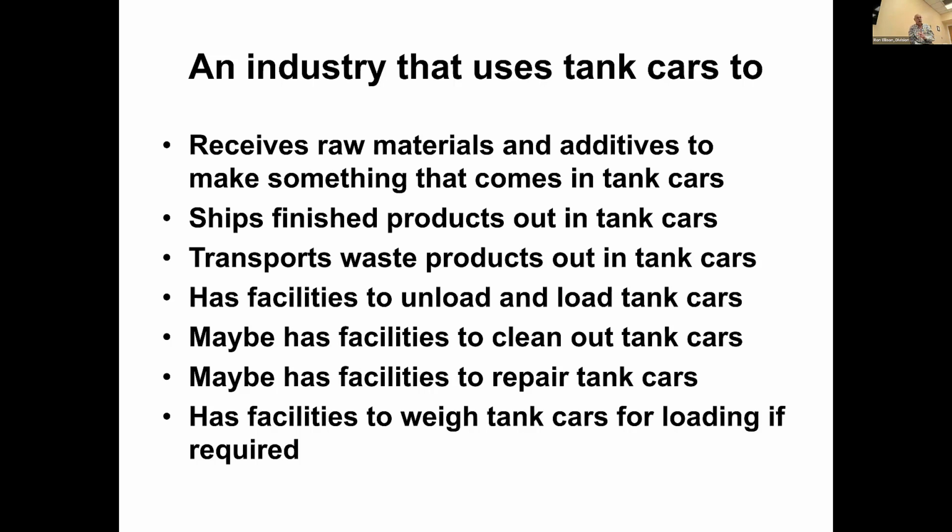And again, I told you also, if you're loading cars in Calgary, Canada, shipped to Mexico, where it's a different temperature between winter and different times of the year, again, as the car goes south and it warms up, that product is going to expand and fill further. And if you overfilled at the beginning, you're going to have an outage somewhere en route where it's going to be coming out of the car. Not a good situation. And that's when the fire service gets called at 2 a.m. Hey, we got a tank car leaking in the yard, or we stopped the train.